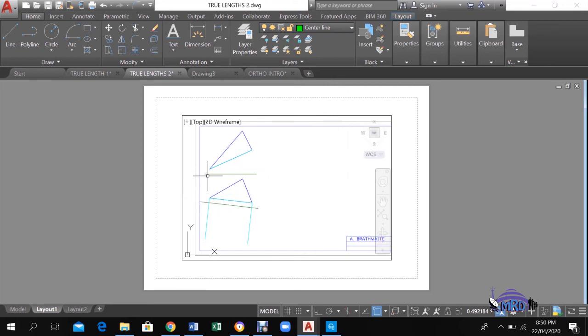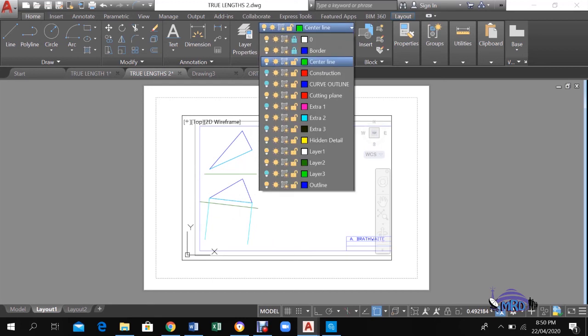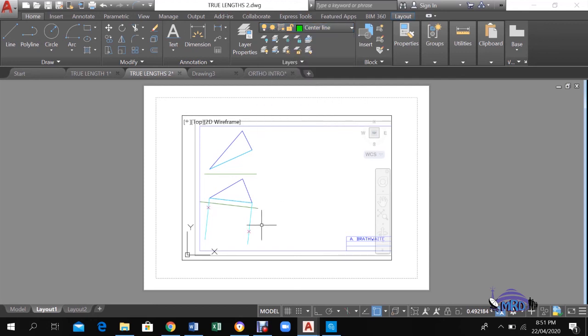And then you know then that you want to take the heights in the front view and bring them down onto the plan, measuring those heights from the XY line. So in this instance, your construction then would show these 2 points, and these 2 points, once connected, would represent the true length of